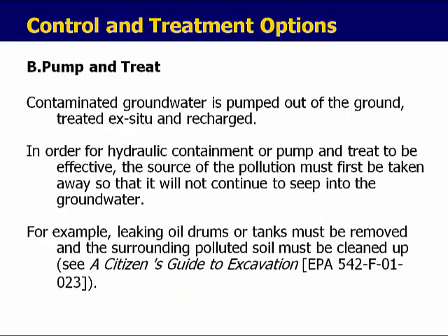The second option is an extension of the first. In the first, we simply controlled the movement of contamination by pumping it. In the second option, we would then treat the pumped water. So the contaminated groundwater is pumped out of the ground and an ex situ treatment is designed. The other option, if you don't treat the water, is to recharge it in deep subsurface where it would not pose a public health risk. This is not as desired as actual remediation and treatment.